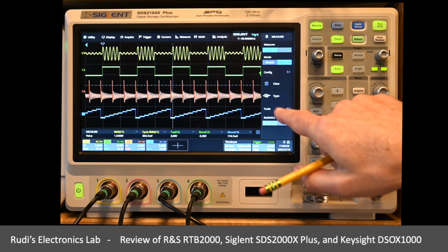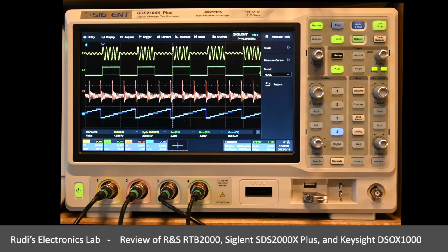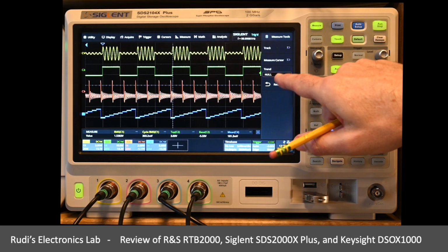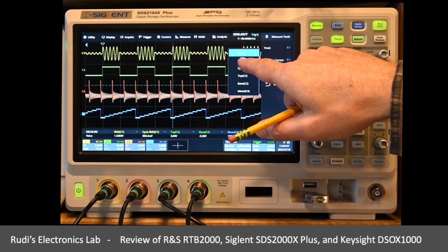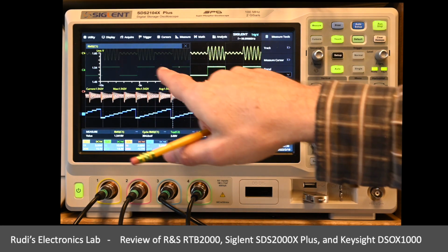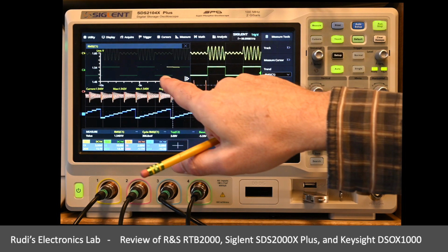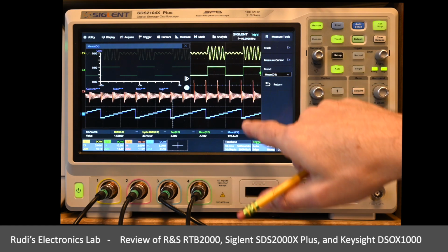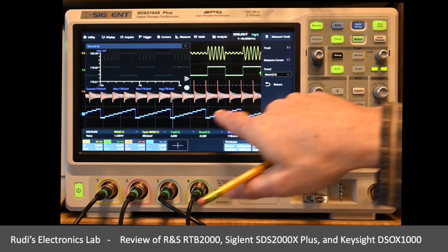We also got a couple of tools here which are called trend and track. And trend is right over here, and we can select a particular waveform, and we get to see a trend window for that particular waveform. Actually, I will be doing the trend for the mean here at the bottom. So that's that value over here.